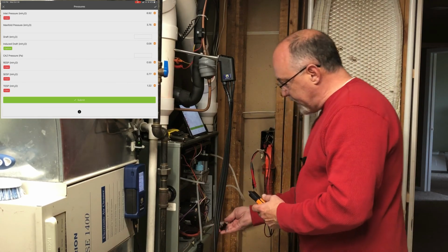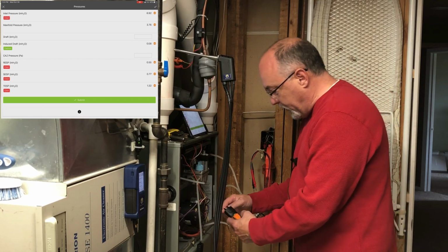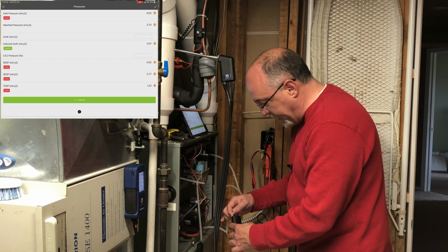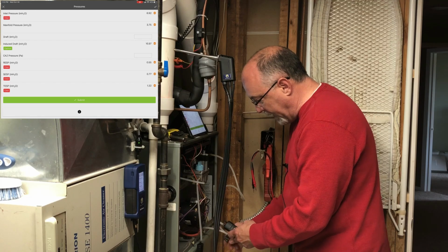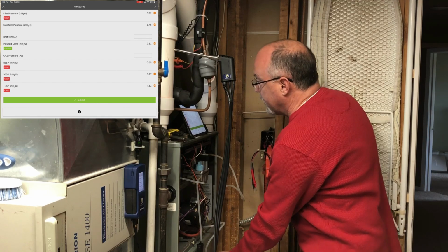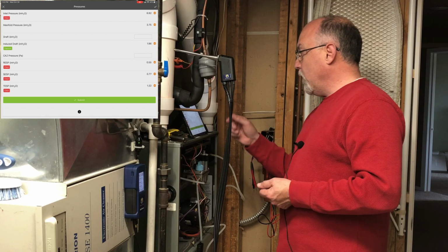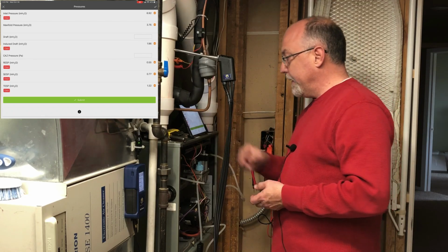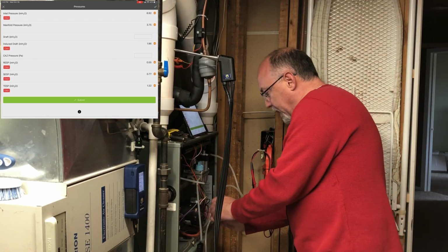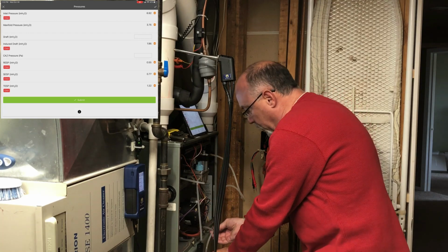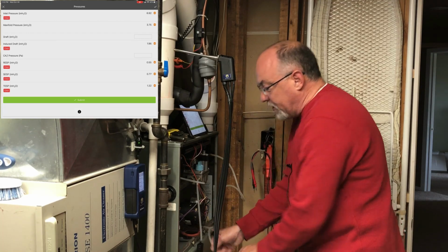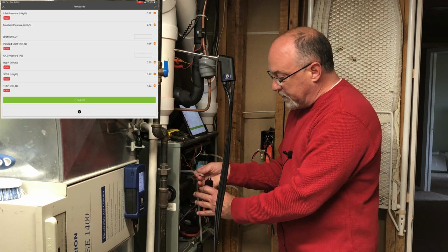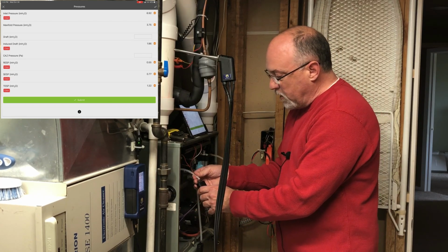Now what I did here is I have a clip, so I can put this on here, and I'll put it on the negative port because it's drawing the negative draft. Then I can open this up and I can read my induced draft pressure on here, 1.97, and I can capture that. So this clip just allows me to remove the manometers and things like that without shutting off the furnace, right? So it just makes it a whole heck of a lot easier to move things around.